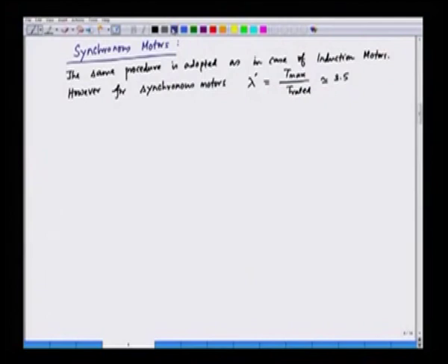Now, in certain situation we have very high peak torque. Now, if the peak torque is extremely high, we will get by this procedure a very high rating of the motor, which is not sometimes economical. So, if the peak torque is very high, we go for what is called load equalization. So, let us see what is the meaning of load equalization and how it is achieved. So, we will be discussing now load equalization.